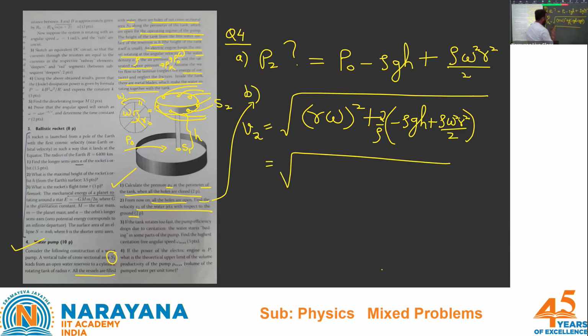And check this. So r square omega square term, and again r square. So it seems like 2 r square omega square minus 2 gh. That should be the answer for B part. Right? So while writing pressure, the rotating frame is fine, but when you are writing that velocity, you have to be careful.